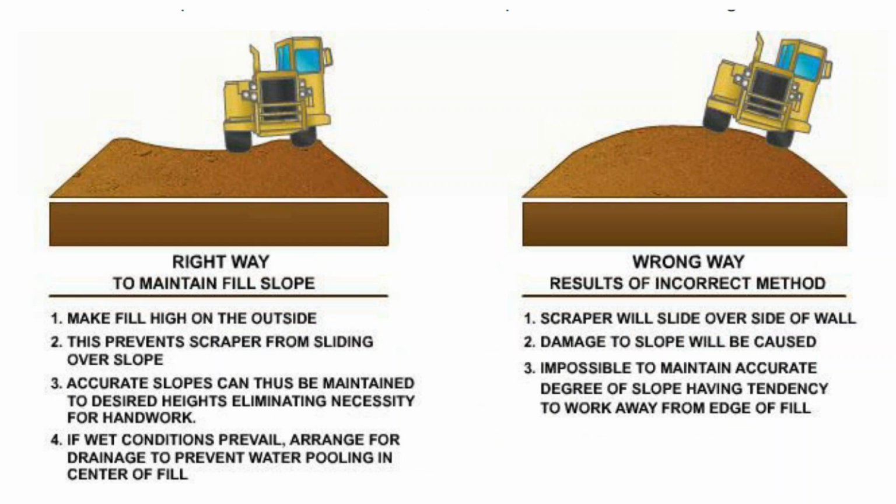There are some safety aspects, of course, to filling. Where you're maintaining a fill slope, you want it to be concave, not convex, which means that you fill the alternate sides and then the middle, not in the middle all of the time. If you do that, you lose control of the slope when you're building it. In addition, it's not too hard to imagine what happens in slippery conditions and in a moment of poor traction: that scraper on the right is going to end up in the ditch.